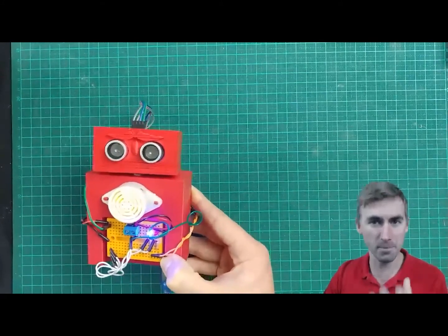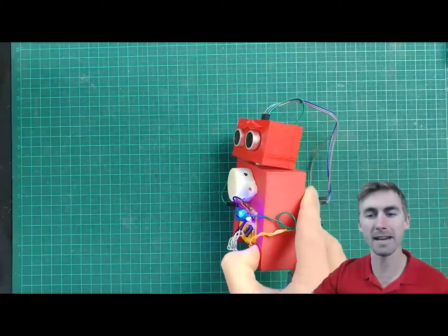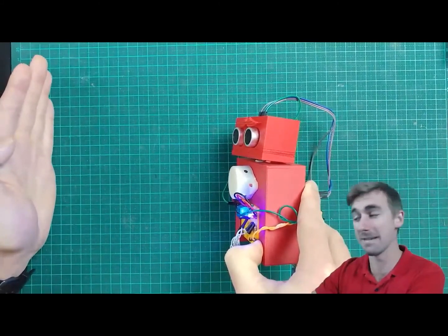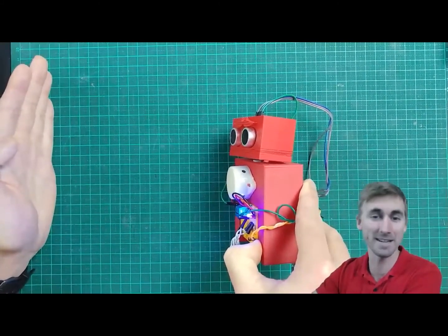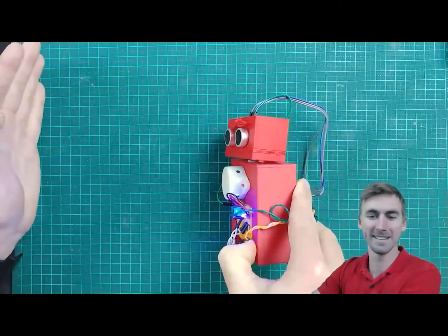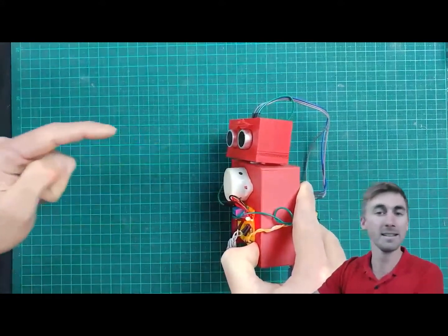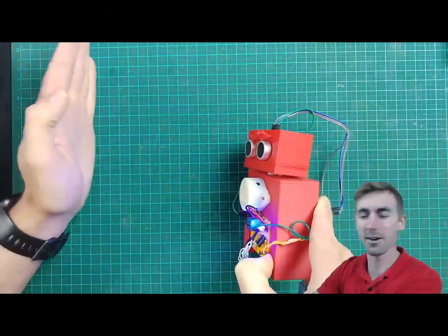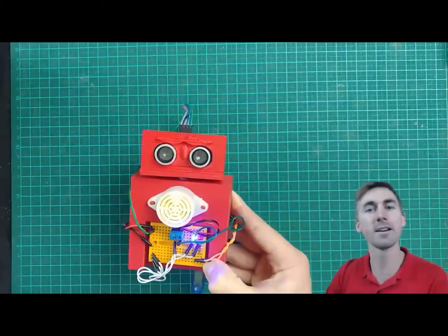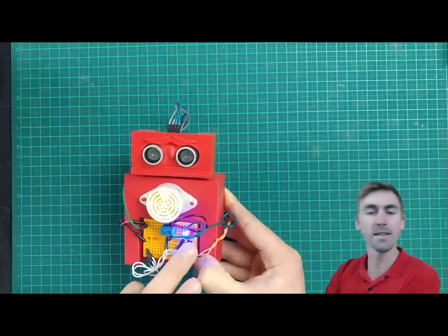So it's called our Spy Gadget Robot because if anything tries to creep up on it, let's say my hand tries to creep up on it, it'll actually alert anyone in a nearby distance that it is having something come up to it. And so that ultrasound has little sound waves that are hitting my hand, reflecting, going back, and then those inputs from that sensor are going back to the control system and then outputting the LEDs and the buzzer.